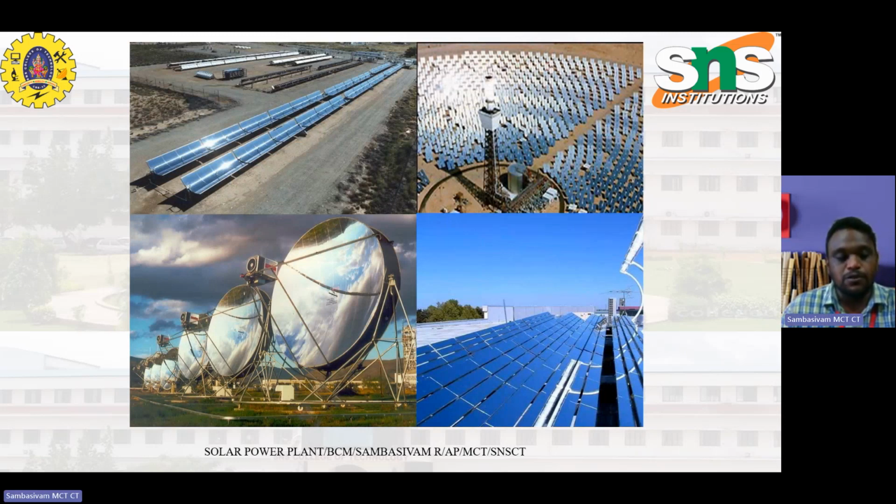Several applications are based upon solar panel creation, as I said earlier. To make solar panels, one requires several solar cells made of doped silicon. As discussed before, these are connected in series to add up the resultant current. This gives a strip of clustered cells called a module. A single module can be used as a solar panel or combined with others where a larger panel is required. A solar panel consists of several layers that sandwich the photovoltaic cells: cover glass layers, anti-reflective layer, contact grid, PN silicon diodes, and back plates. An aluminum frame is used to hold the panel and make it weatherproof.